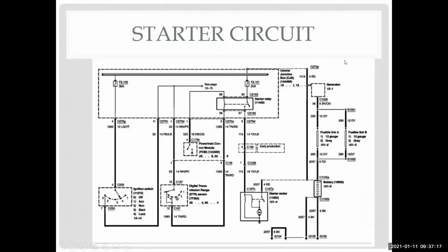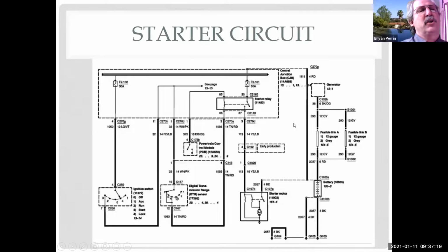Yep, I like that. And I also do this to show commonality. So here I have a starter circuit. And here's my ground. We know ground's normally at the bottom. Here's my battery. So kind of interesting. My battery comes up and this dashed line between these circles meets, this is all the same splice. So these are connected together. If I bring this wire up, it's also connected right over to this fuse. And I can see I have another fuse here. So they put the power at the top, the ground at the bottom, and I have an ignition switch.